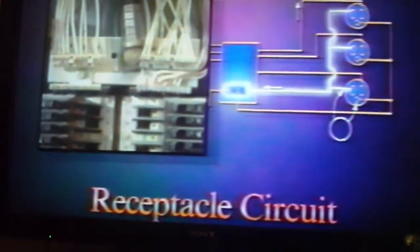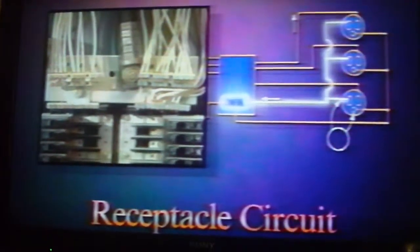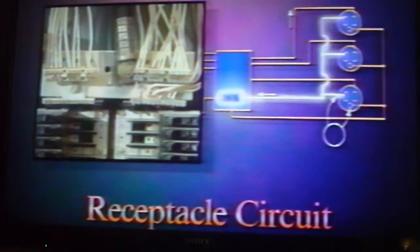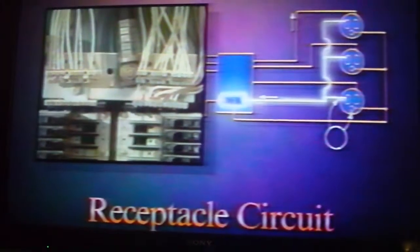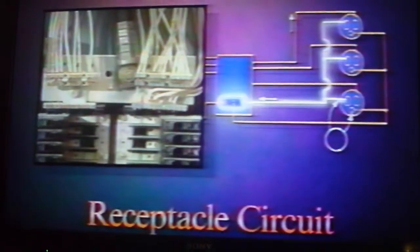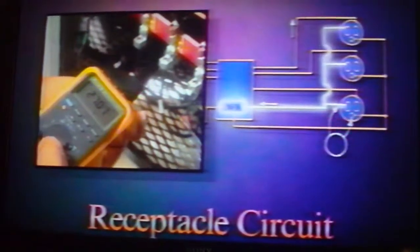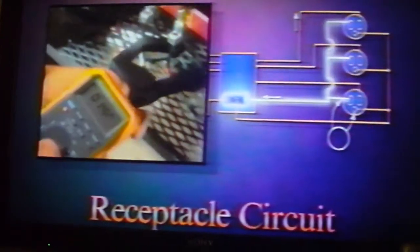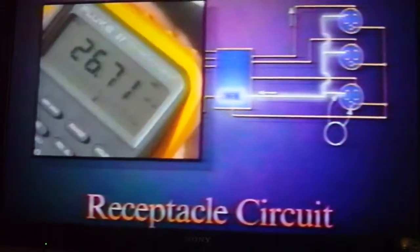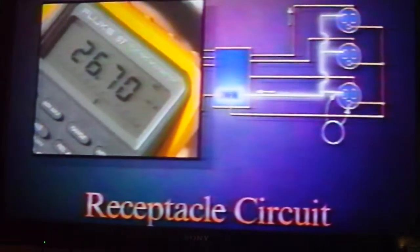Shared neutral conductors in a three-phase system can be severely affected by nonlinear loads connected to the 120-volt branch circuits. Under normal conditions, for a balanced linear load, the fundamental 60 Hz portion of the phase current will cancel in a shared neutral conductor. However, triplen harmonic currents add together rather than cancel in a shared neutral, which results in neutral current that can be greater than the phase current, even if the loads on the phase conductors are balanced.